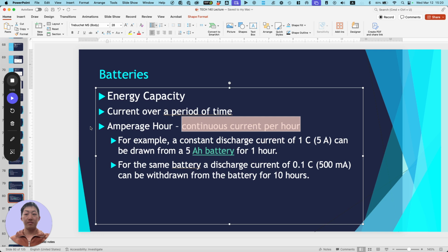Again, just the baseline. Yeah, take a look at it. And you also want to measure it when the battery has cooled down. Don't do it when it's hot, just like you don't measure your air pressure when it's hot. You want to let it cool down a little bit. So same thing here. We don't want to get a false reading.